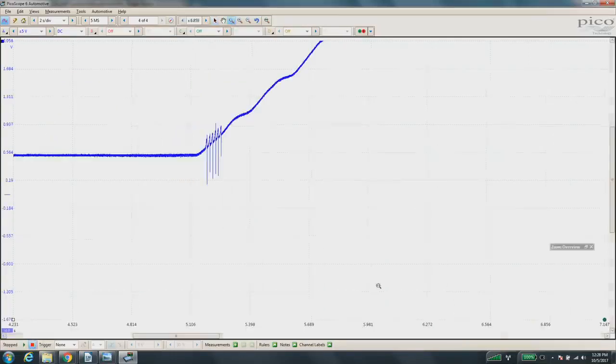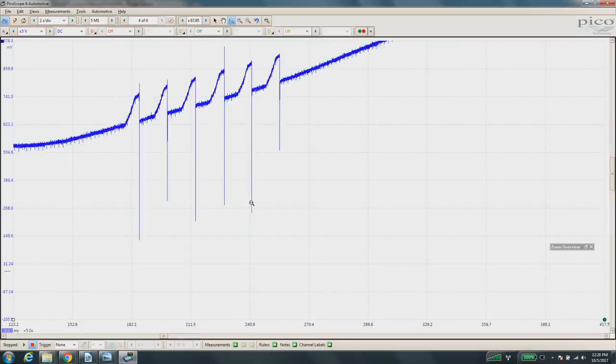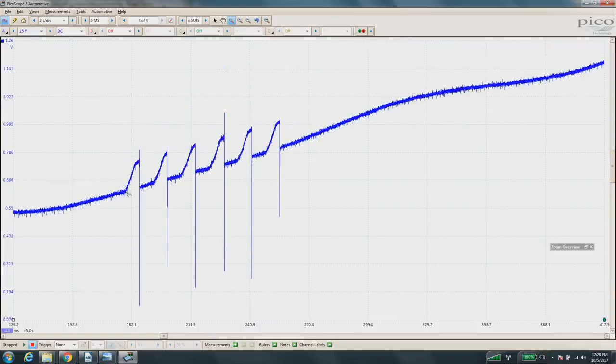Right here's an issue in our signal, right? We would have never seen this on our meter. Our meter's not fast enough. This is a problem right here. Our voltage has changed. Now, our spec is in degrees. We would have to correlate that to voltage, but it's in a 7 millisecond window. So let's just see how fast these issues are coming up. If that's considered our issue, I would say that's roughly right at that 7 millisecond mark. Right? So we have issues in this sensor. I'm glad we were able to at least see something here.